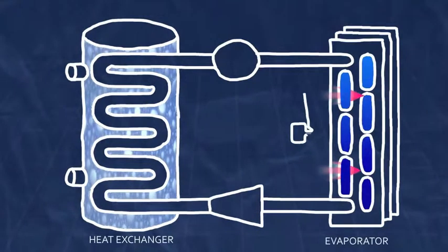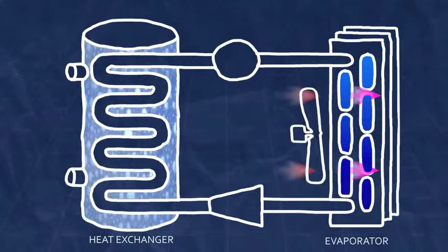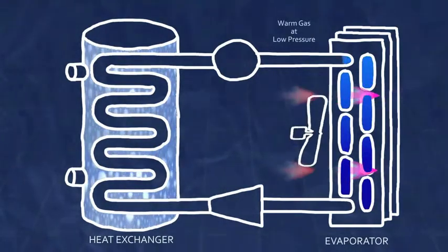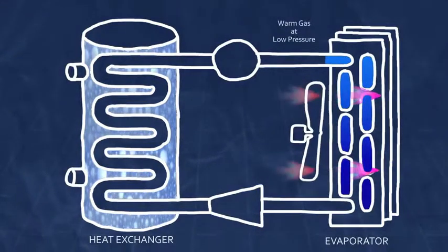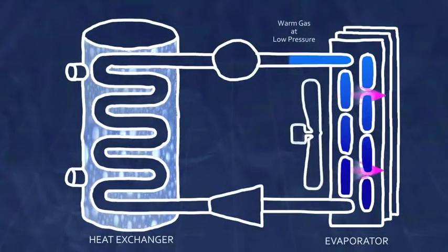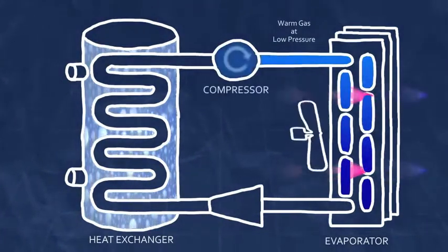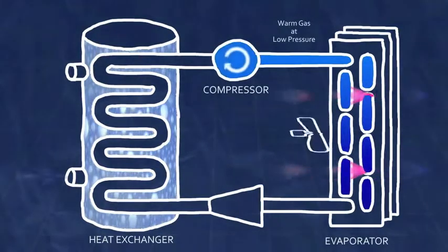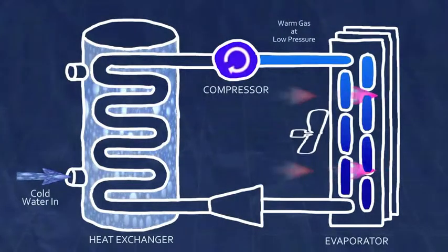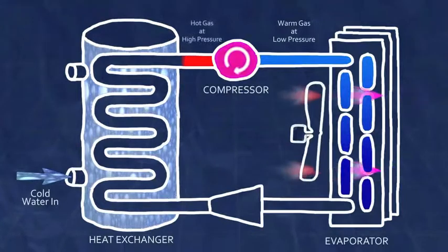This heating is expedited in the evaporator, with many fans designed to blow the room temperature air over the tubes holding the refrigerant. The heating, using room temperature air, causes the refrigerant to become a vapor, flowing into the compressor from the evaporator. The compressor, which increases pressure, heats the vapor to the extent where it can be useful. The compressor then forces the now hot refrigerant into the condenser, which holds the water that will be heated.